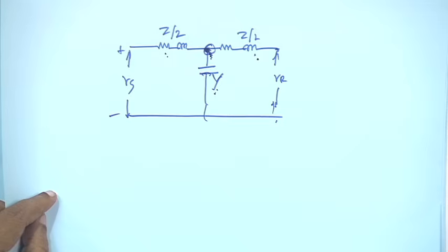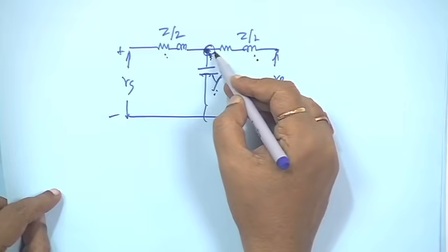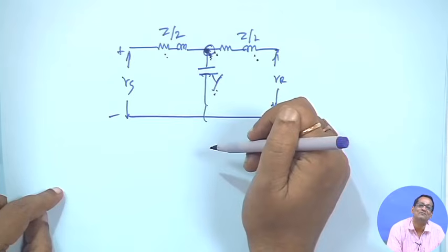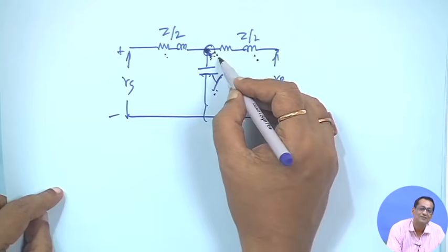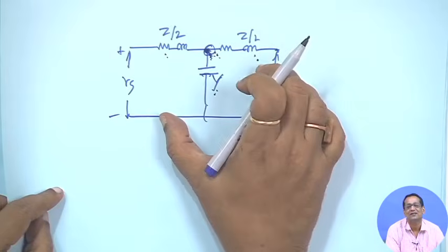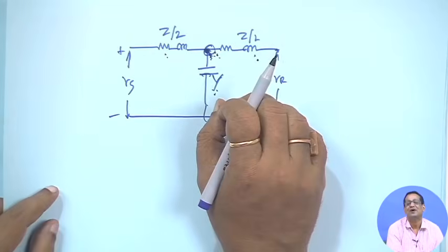In a power system, so many nodes and bus bars are there, and so many lines are there. For each line, one additional bus bar you will create, and this will increase the dimension of the problem. That is why we do not use the T network for line modeling; we will use the pi method.